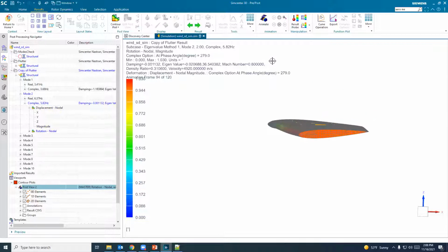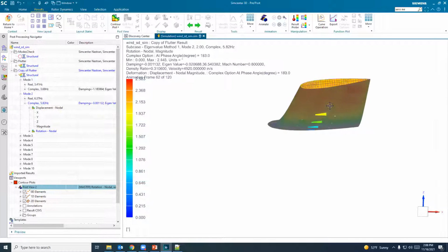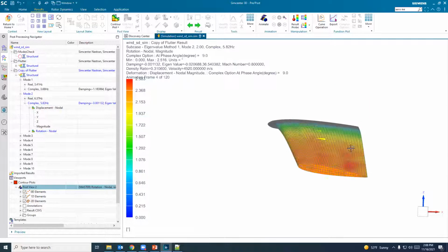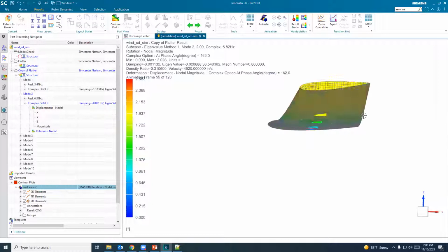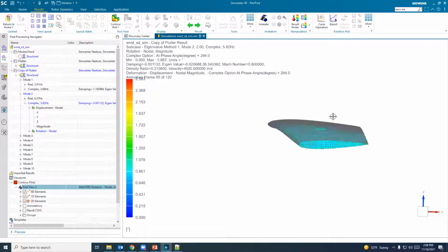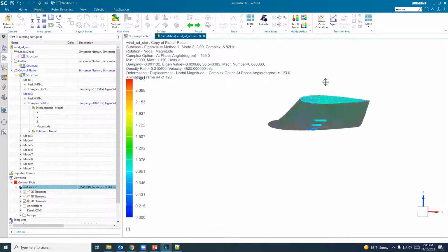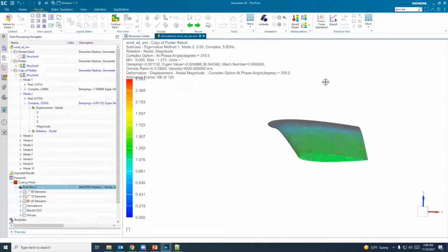And what you'll see, if we look at this airflow cross section of this model, is that we get a pretty similar result to what we saw for the 2D section. So there's a connection there. Again, we see this sort of response where, if we make the assumption that would only be valid at basically zero reduced frequency, that the force is in phase with pitch, which we know isn't exactly true, since there are plunge rate terms and pitch rate terms affecting the kinematic angle of attack, and also shed vortices that change that. But just for the sake of a shortcut,